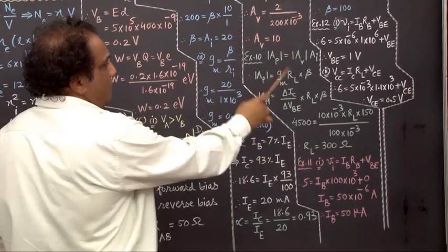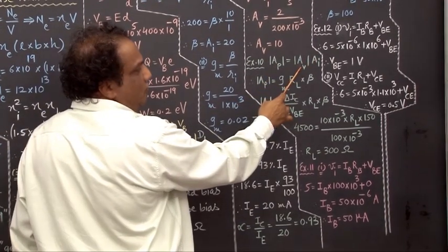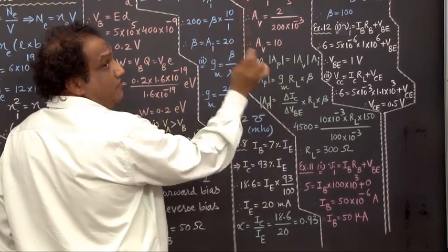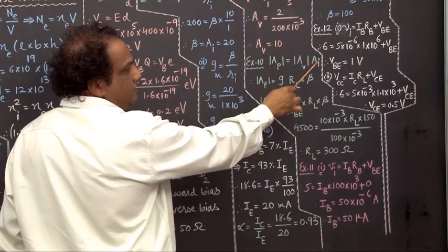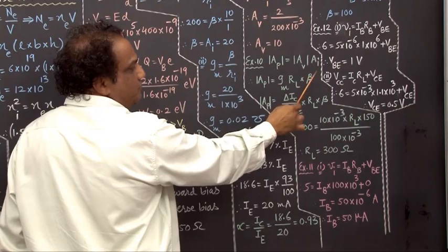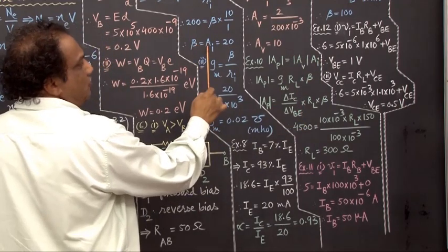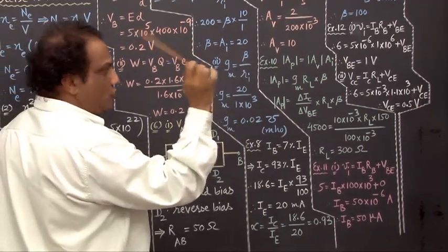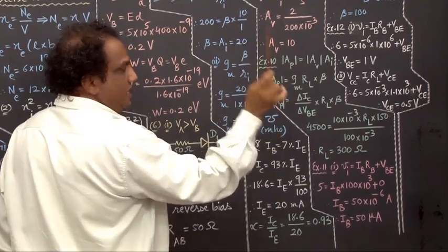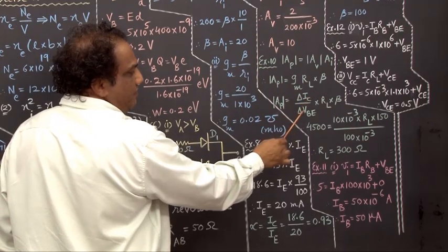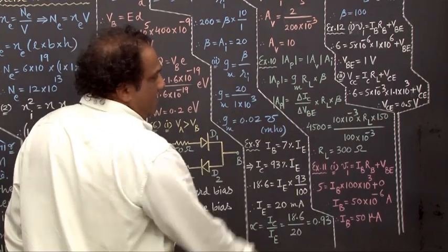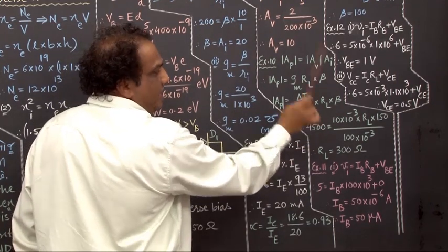Read it. Come on, magnitude of power gain is equal to magnitude of voltage gain multiplied by current gain AI. Now magnitude of voltage gain by formula is gm into RL, and this AI can also be shown by another symbol, beta. Instead of AI I am just putting beta. Beta and AI both indicate current gain in common emitter mode. This is the formula for AP as it is. What about transconductance? Its formula is change in collector current divided by change in base voltage. So come on, delta IC upon delta VBE, and into RL as it is, into beta as it is.